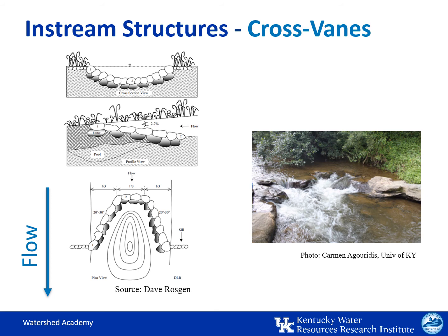Often cross veins will be placed above or below a meander to establish elevations for pool and riffle formation. Many fish species use these pools as areas of refuge because of the increased water depth that forms below them, and they're prime feeding areas for items washed into the pool from the riffles.